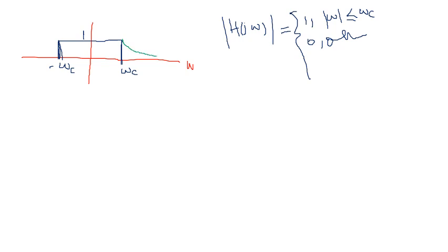Depending upon the order of the filter, we will not go into much detail here, but we'll talk about the point where the magnitude response |H(jω)| equals 0.707. You understand it is dropping with the frequency, because it's a low pass filter. If you move from 0 up to a certain range, in the case of an ideal filter up to omega c, which is its cutoff frequency, it will remain 1 and it drops down within no time to 0.